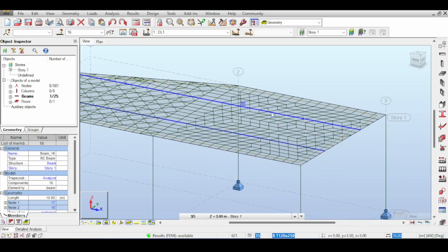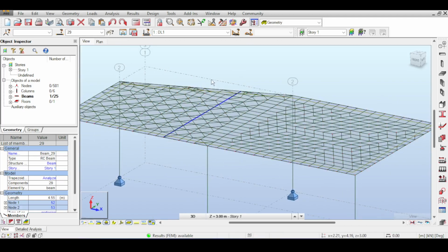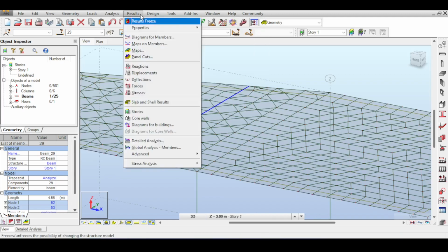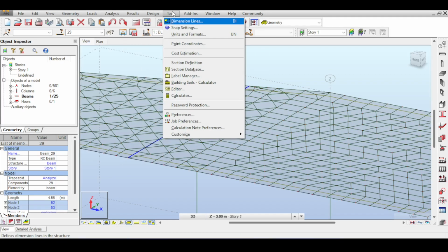If you want to do a simplified analysis, you would basically use WL square over 8 and try to find W, the load, by distributing the force somehow. Now, this is not 100% accurate, and allow me to show you what you are missing. If you use WL square over 8 on this rib, you are missing a negative moment due to the torsional moment of the carrying beam. This seems to be strange.